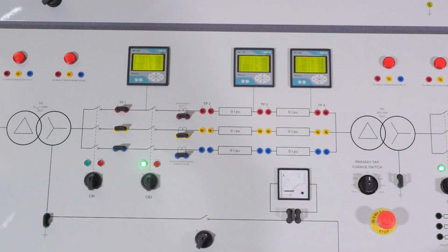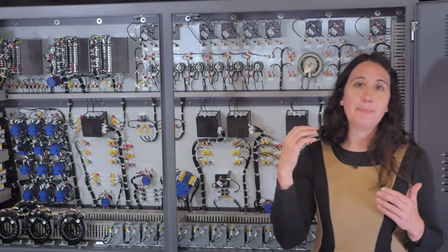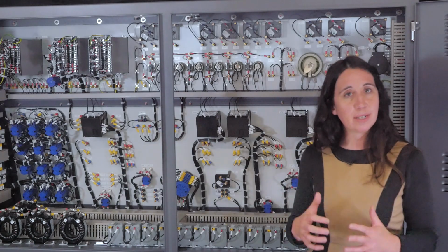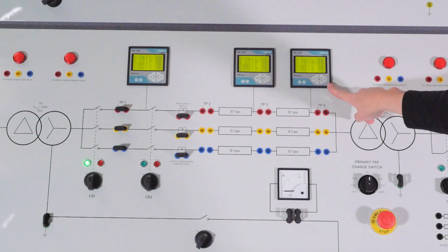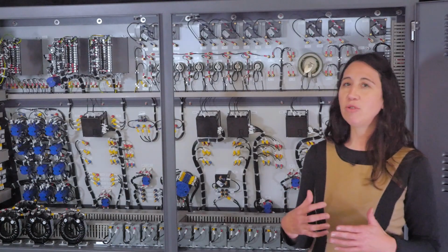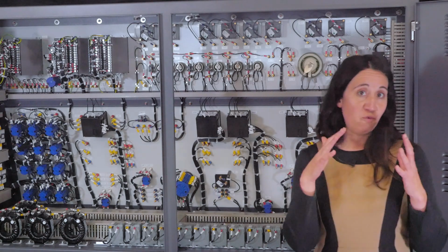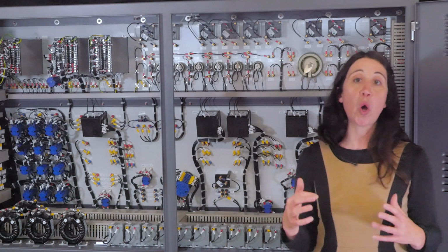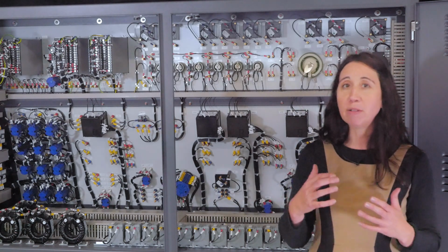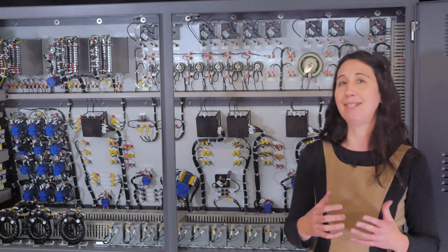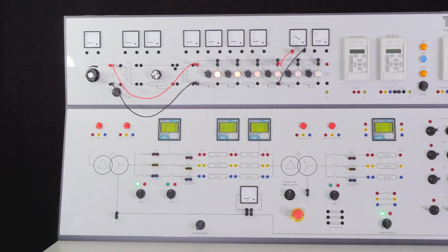The feeders are represented using the per unit system, a way of building a simulator so that it behaves the same as real-world systems. The three-phase line has multifunction measurement centers that measure up to 32 electrical quantities, including voltage, current, and the 3 powers, real, reactive and apparent, all on 3 phases. The 4 digital multifunction meters are identical in their measurement capabilities. All are connected to the line by current transformers.